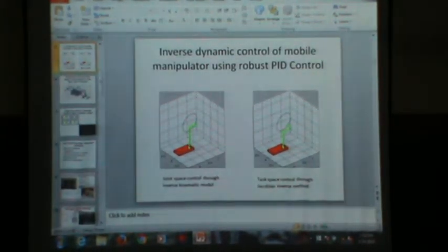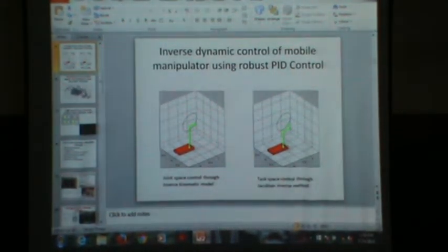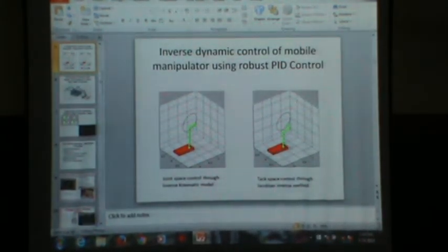This kind of dual loop scheme will work and will minimize the error, even if it is friction, kinematic error, clearance error, or backlash error, which will be overcome easily. Even if you use the same system for probably 10 years, this particular control scheme will work the same way for all 10 years.